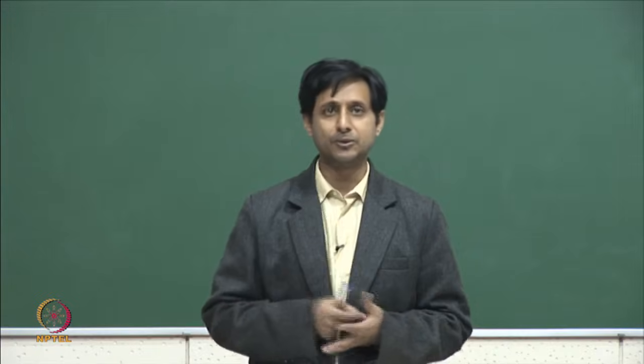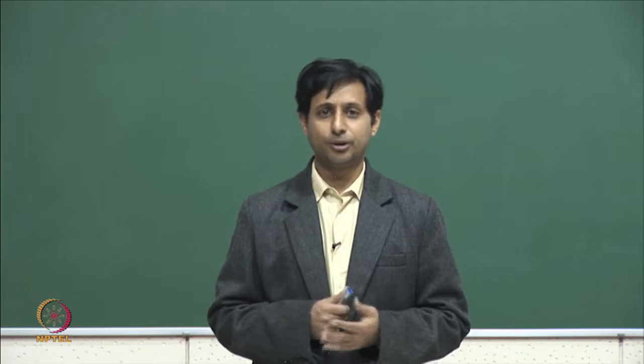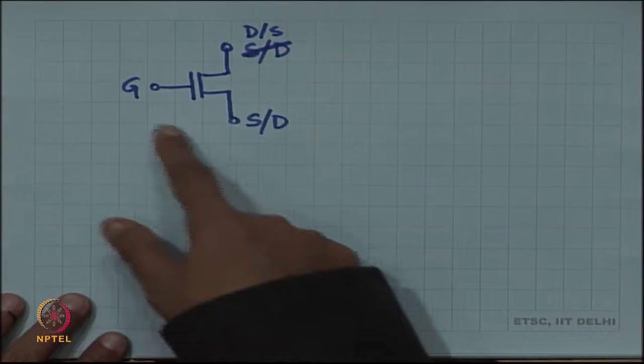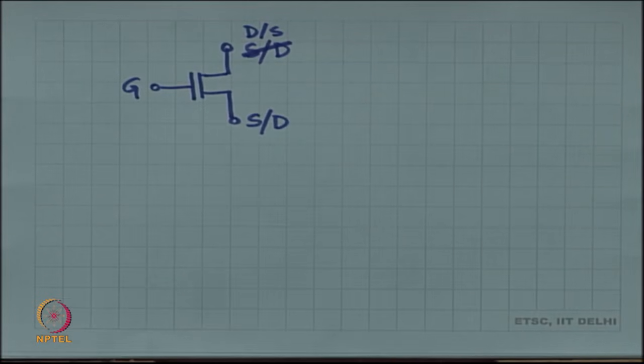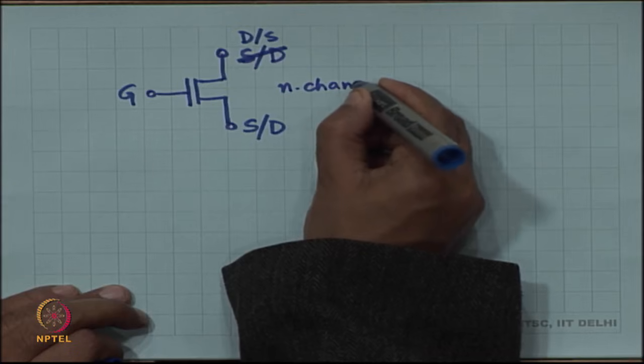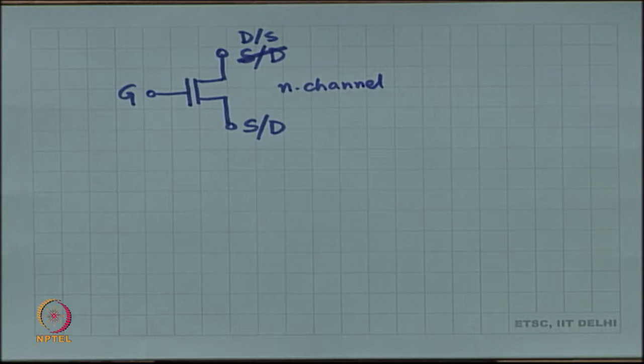So, the connection between source and drain is either a short or an open, all right. So, that is the likely operation of this circuit when the MOS device is drawn in this fashion, that is what it probably is being used for, it is being used as a switch. Okay. And this particular device is N channel, all right, that is the symbol.